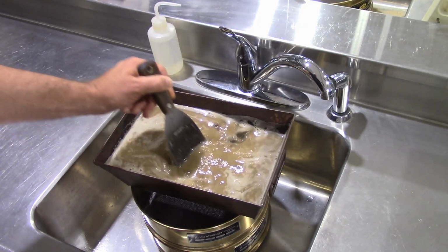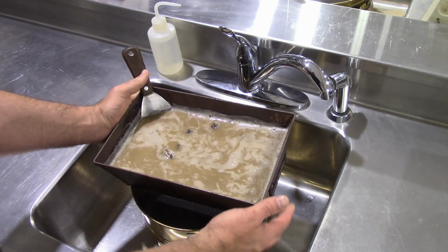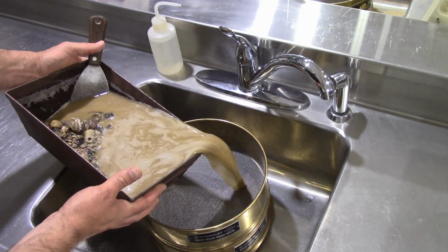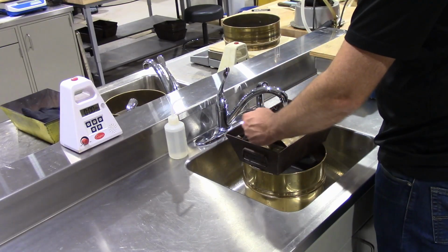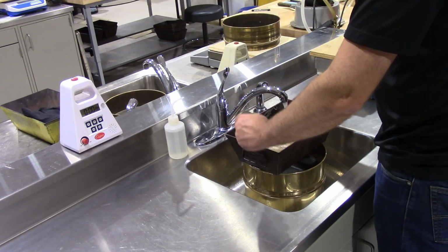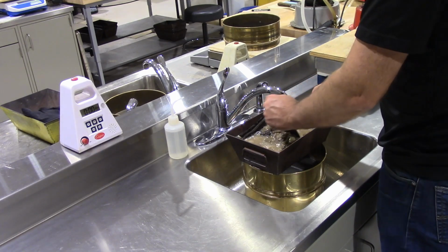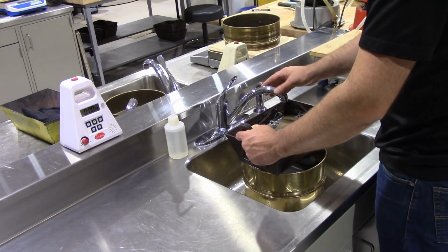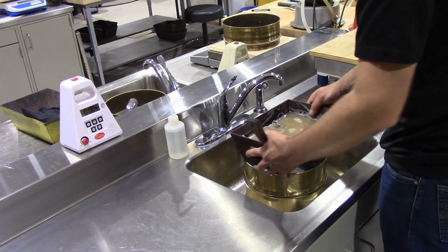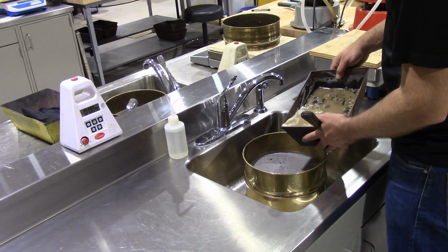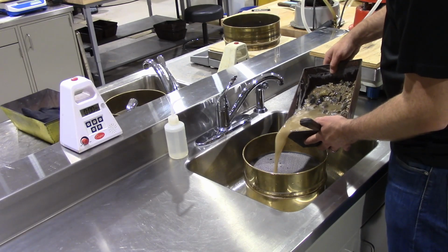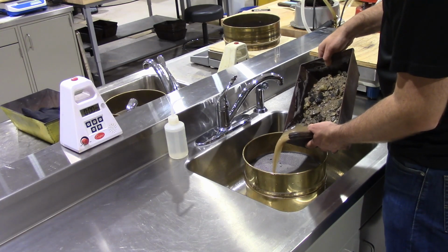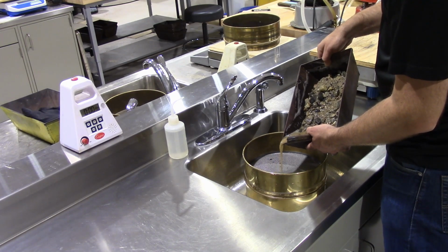Allow the water to saturate the sample. It is our goal to allow every particle of dust, or P200 material, to pass through the sieves. Stirring and agitating the sample will aid in this process. The purpose of this test is to determine what percentage of material is smaller than the 200 sieve. Everything that goes down the drain is smaller than that bottom sieve and is lost to the drain. That is why this test is called the loss by wash procedure.